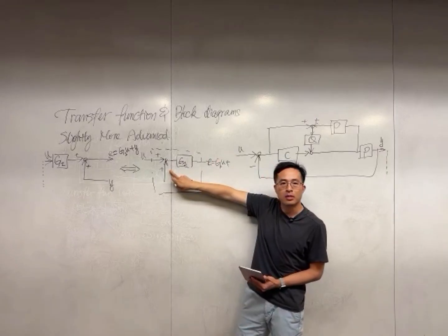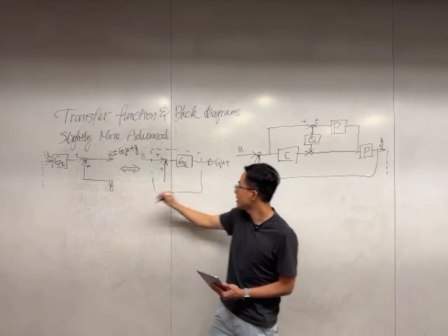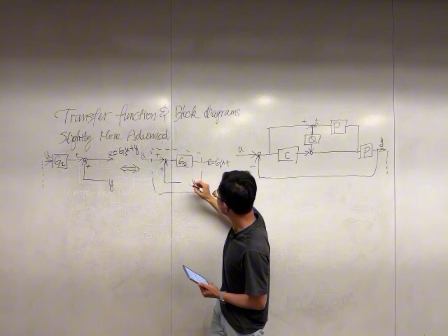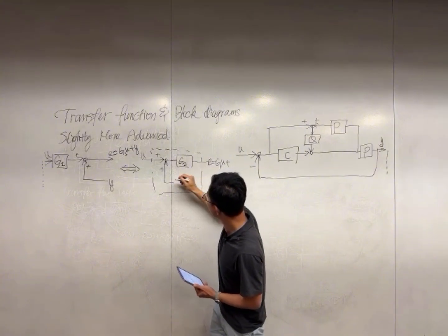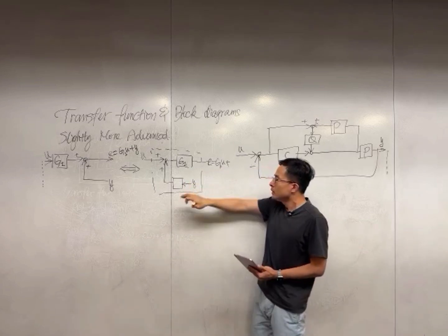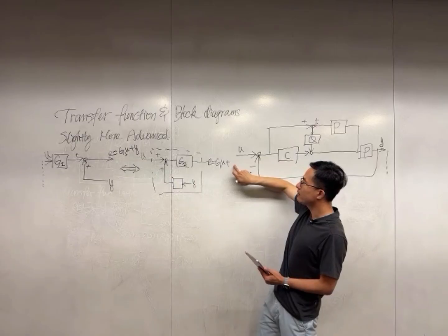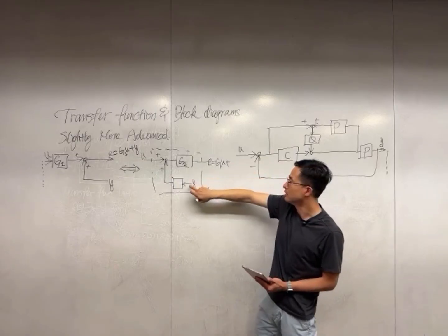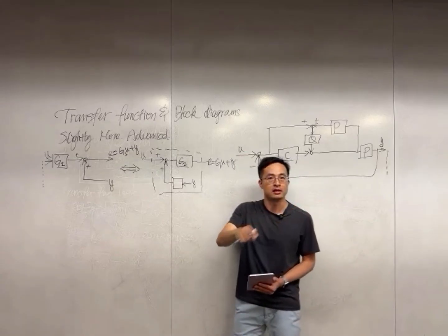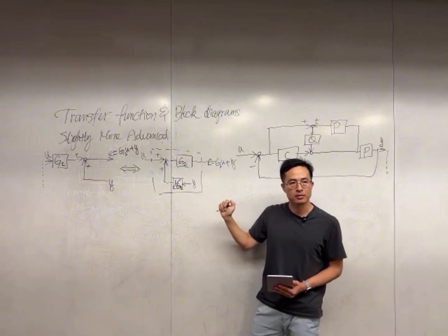And then in the bottom over here, let's say this is Y, okay? So what should this block be in order for whatever I add up in the end, I will still get a Y? I'll answer a question in a minute. All right? So that's 1 over G1. That's how you move a summing junction.